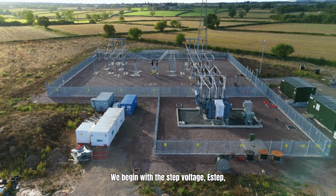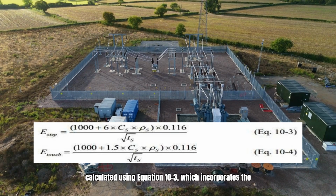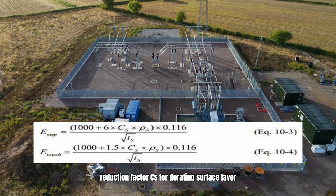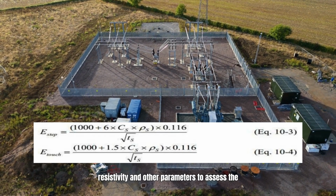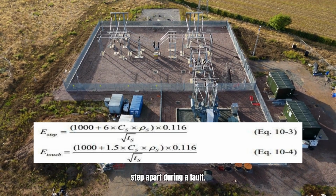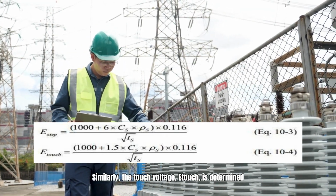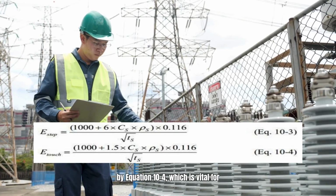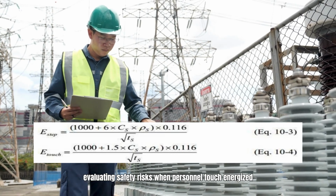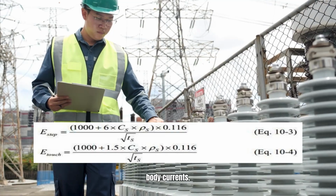We begin with the step voltage, E-step, calculated using equation 10-3, which incorporates the reduction factor Cs for derating surface layer resistivity and other parameters to assess the voltage potential between a person's feet a step apart during a fault. Similarly, the touch voltage, E-touch, is determined by equation 10-4, which is vital for evaluating safety risks when personnel touch energized equipment and grounded structures simultaneously, preventing harmful body currents.